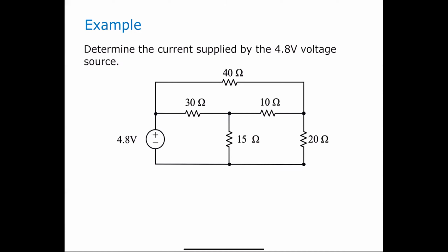Oh, yes. Is it the 30 ohm and the 15 ohm? Sure. 30 ohm and 15 ohm, no? So let me test that. They're interconnected at one point, but there's another element that is also connected there, no? So by definition, when at the point of interconnection of the two elements there's another element connected, that is no longer in series. Anyway, good try.